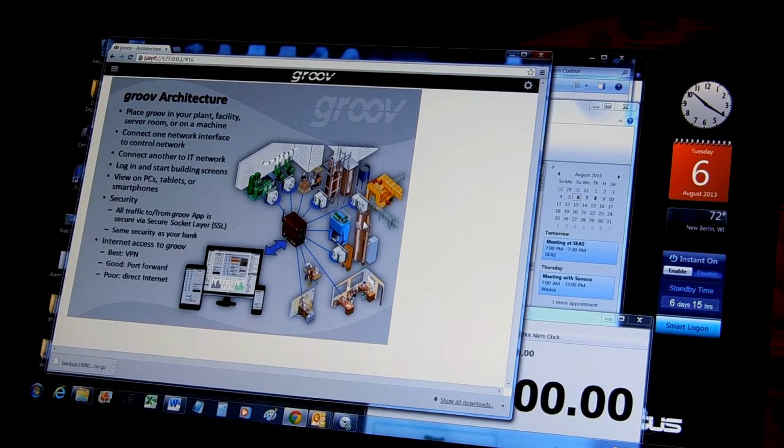For Allen Bradley, specifically, we provide a bridge that connects the Ethernet IP to the Groov. But most exciting of all is our coming support for OPC UA. This technology allows Groov to work with any system that offers an OPC UA server. Groov will be an OPC client that talks to the OPC server. That is going to be huge.